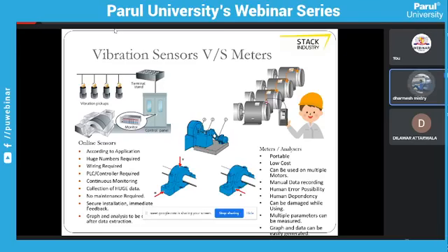On the right side, I have shown a person standing with a handheld device which is connected to a single sensor. What is this handheld device? For right now, I will discuss the continuous online sensors. I will give an example in the paper industry. In a single line, there are more than 475 vibration sensors in a single machine, because in a paper industry everything works on bearings.